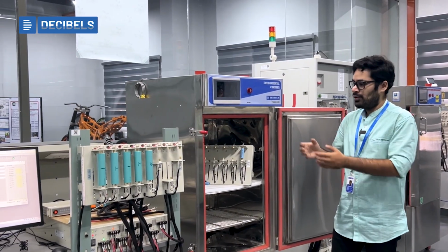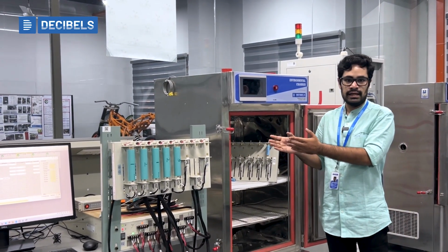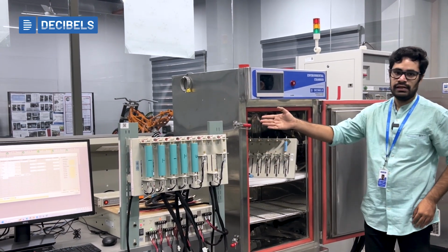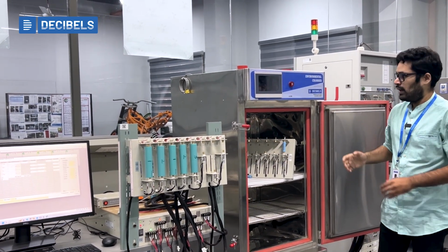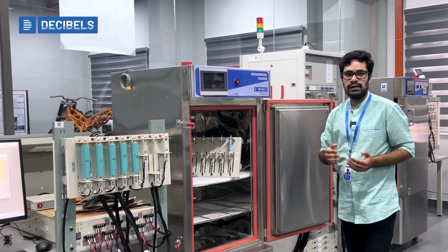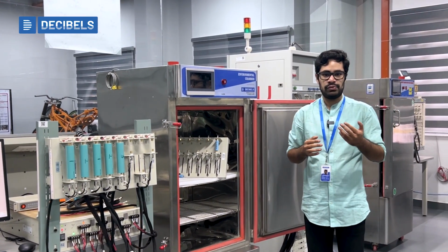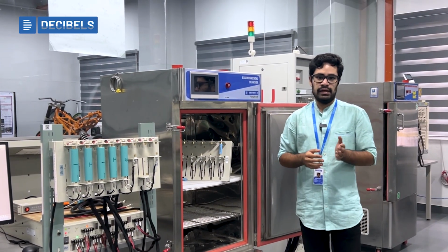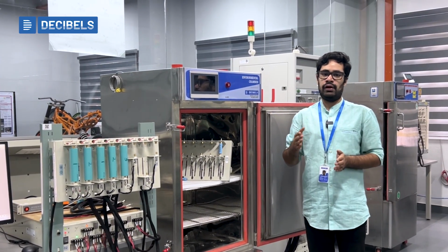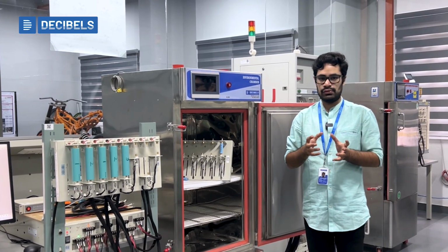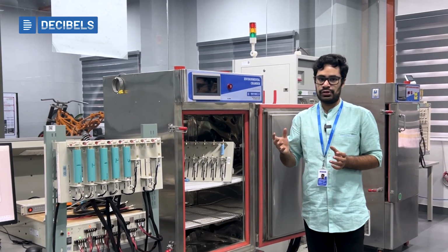We use a data acquisition device with a cell testing machine, a newer 5 volt 20 amps machine that we can see here along with the software. And here is the climate chamber, also known as the environment chamber, where we can set the ambient temperature anywhere between minus 25 degrees Celsius and plus 95 degrees Celsius. Again, the intervals we have chosen are 0, 25 and 45 degrees Celsius, and by performing this test, we get the characteristics of the cell at each of these temperatures.